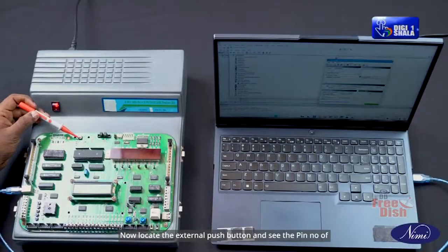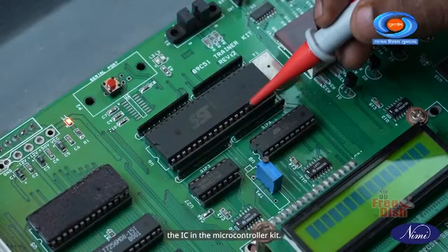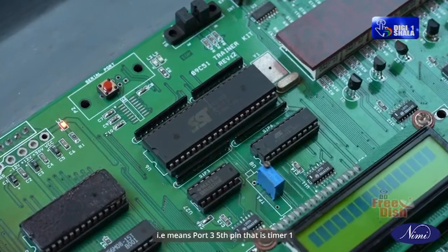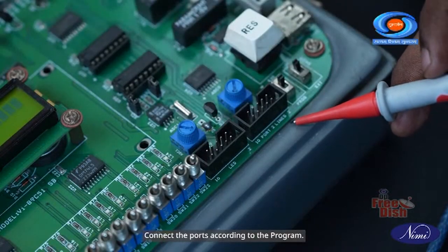Now locate the external push button and see the pin number of the IC in the microcontroller kit. Here, it is connected to pin 15 of the microcontroller kit. That means port 3, 5th pin, that is Timer 1. Connect the ports according to the program.